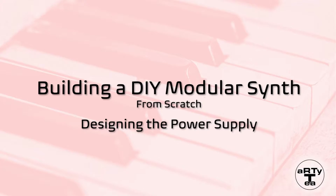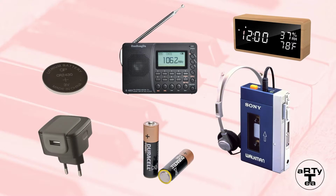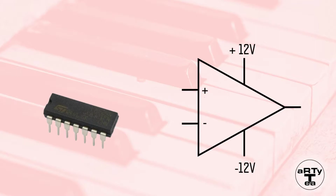While most devices run on a single level power supply, our synth modules typically need two power levels to be able to operate, plus and minus 12 volts. Why is this different from your normal portable device with, for instance, a battery, providing only one voltage? In other words, why do we need that extra power level? The answer lies in the fact that most of the synth modules use op amps. To do their work properly, these op amps need a positive and negative power supply.